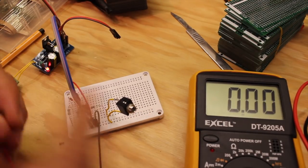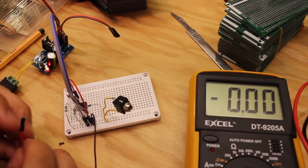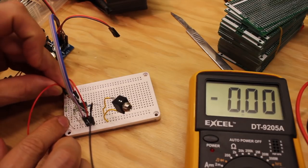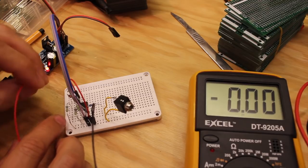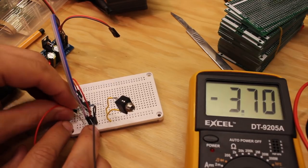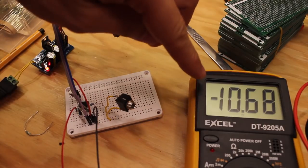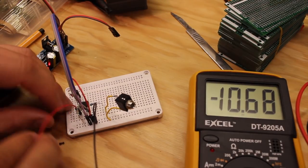And that means that we have nothing on the input right now, so the output should technically be minus 12 volts. It is in fact 0 because we have a diode here. But if we remove that one and just check the voltage on the output pin of the OpAmp comparator, it is minus 10.68, so about minus 12 volts.